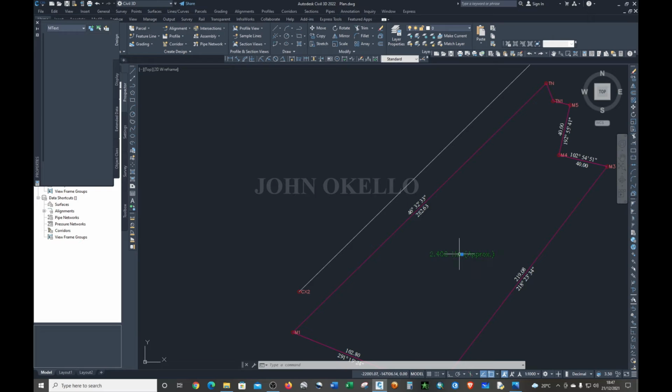So for parcel, just going to select parcel. Under properties, change the font color to white again. Leave it as this, but the style we're going to change to style 2. That's a bold. So we can just increase the font size to size 3.5. Click enter.